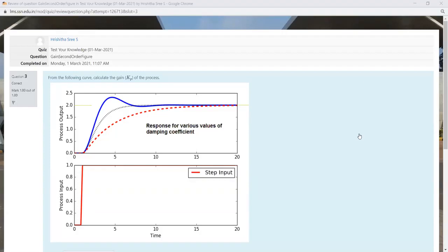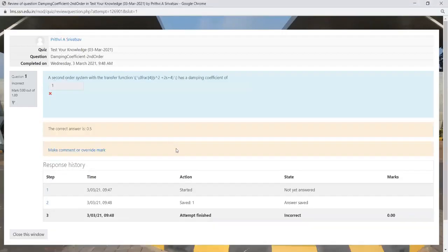Okay, Vignesh has answered. I'll take this. Sometimes I'm considering this simply attendance, but you can easily work out this problem at least, no? So how do you find the damping coefficient of the system for today's problem? Just divide by 4, bring it into the standard form, and equate coefficients. Fine. First, this tau you can easily find, because tau square is 1 by 4, from which you can get tau equal to 1 by 2, and 2 tau zeta is equal to how much? It is 1 by 2 only. From that you can get zeta.